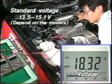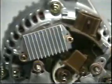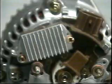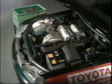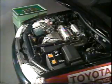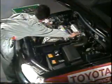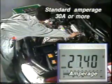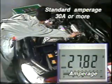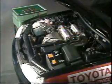In this test, if the generated voltage is higher than the standard, recheck after replacing the regulator. If all voltage generated by the alternator is within standard, you can make your final determination of the charging system condition by doing a with-load test. In the with-load test, if the amperage generated by the alternator is at standard or below, you can assume that the alternator is at fault and inspect or repair it as necessary.